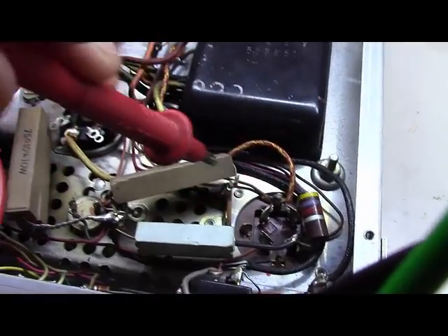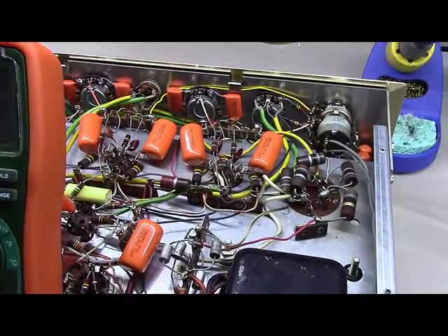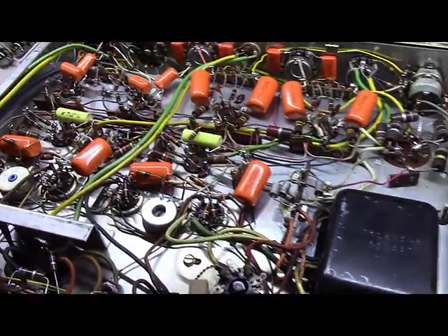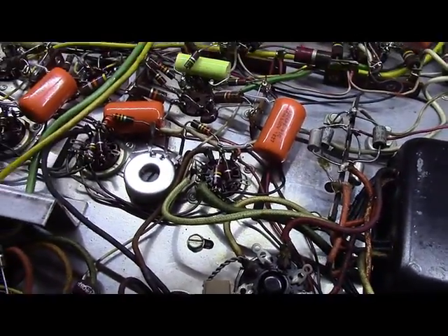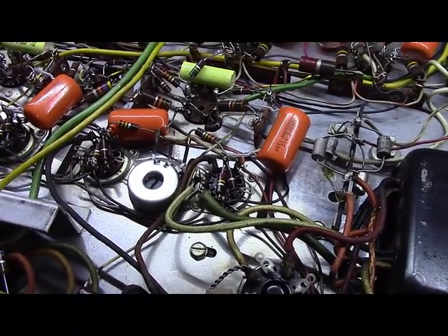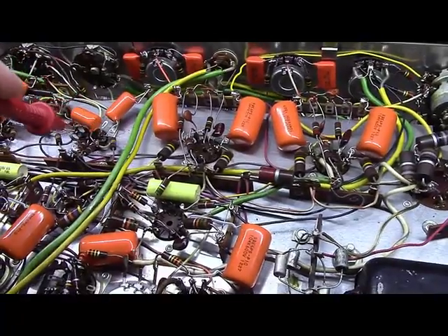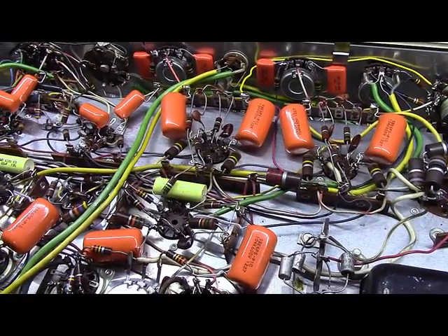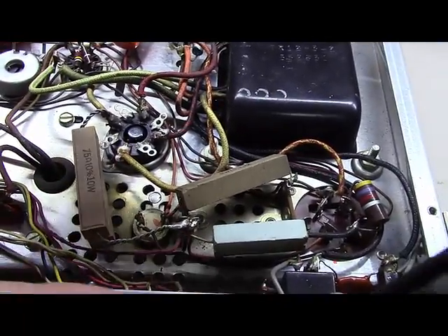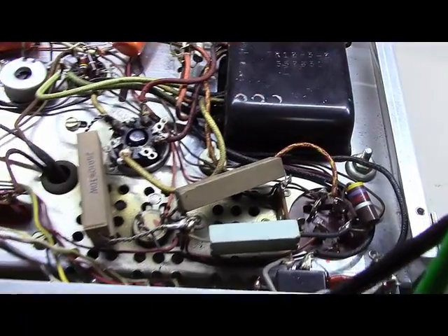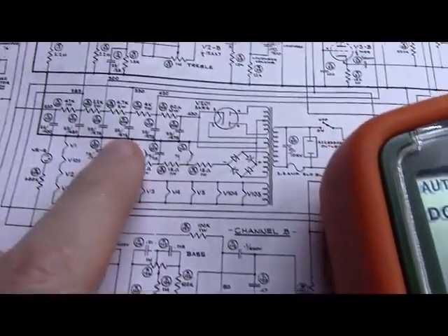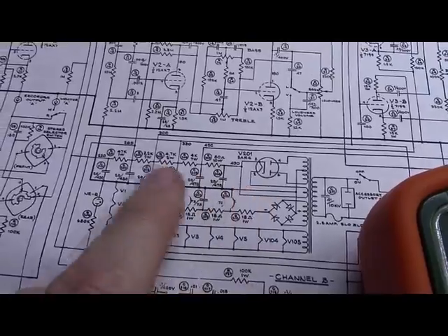And then from there, wires lead out of this and feed off into various places inside of this thing. In some cases here, the high voltage, 400 and some volts, ends up feeding the plates on these output tubes right here. Some of the 330 volts ends up going up here on the front end to some of the 7199 or 12AX7s that feed the front end of this amplifier. So what you saw on that schematic is kind of everything you're seeing here in this little section right now. That's what it looks like in real world. This right here is what it looks like in the schematic, if that makes sense.